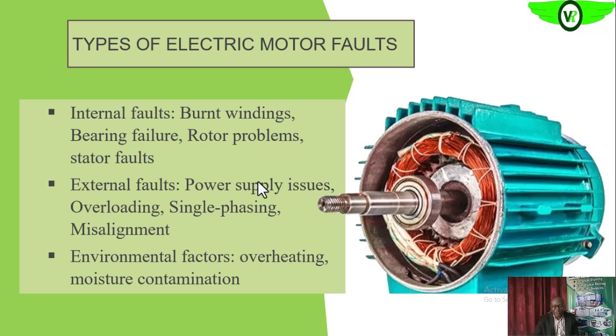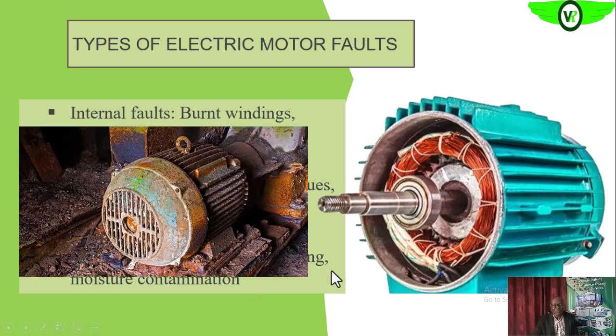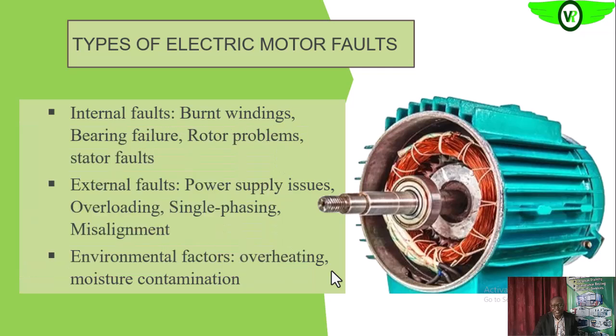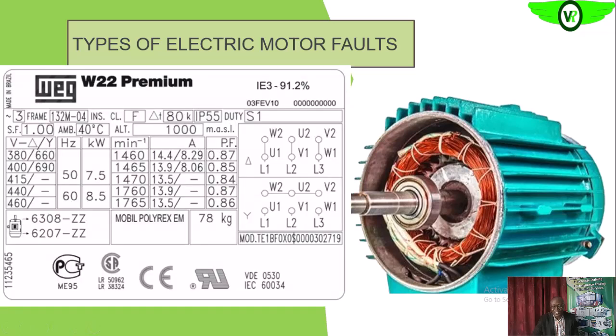Then environmental factors can also contribute to electric motor failure. The ambience in which the electric motor is operating is very important, because these motors are designed to operate efficiently in an ambience that is not above a certain level, for parameters such as temperature and humidity.